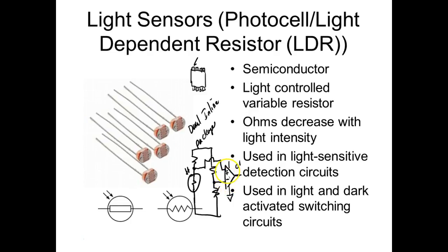So this guy, the output moves in the same direction. This guy, it moves in the opposite direction. Does that make sense? So if the comparator is referenced to circuit common, then if the inverting input is greater, it'll go to 0. If the non-inverted input is greater, it'll saturate to whatever voltage you put up here. So I could put any voltage like 20. Well, it depends. You'd have to look at the comparator and see what the maximum differential voltage between this guy and this guy is.